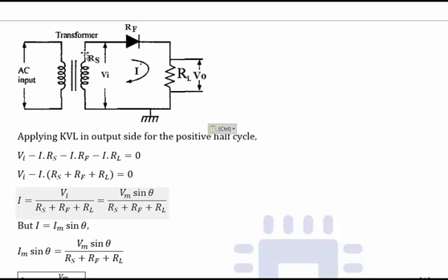If the upper side of the secondary becomes positive, the current will leave from it, and from down to top we will see a rise in voltage. So we will see a rise in voltage at the secondary, and we will see a drop at RS. This is actually the internal resistance. It is not shown here with a symbol. Actually it is the internal resistance of this winding. So we have to imagine a resistor symbol here, of which the value is shown here as RS. So we get a rise here, and we get a drop at RS, then a drop at RF. Drop means plus and then minus, and we get a drop at RL, plus minus, and we get a rise here, like this, minus and then plus.